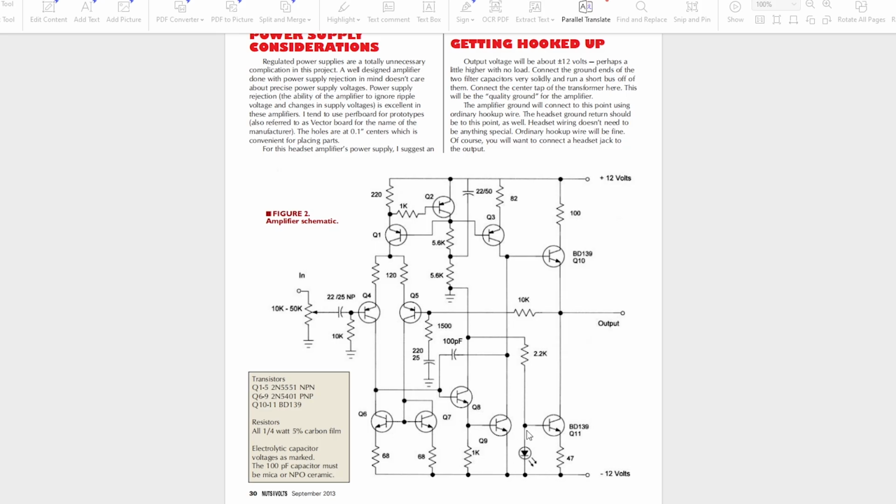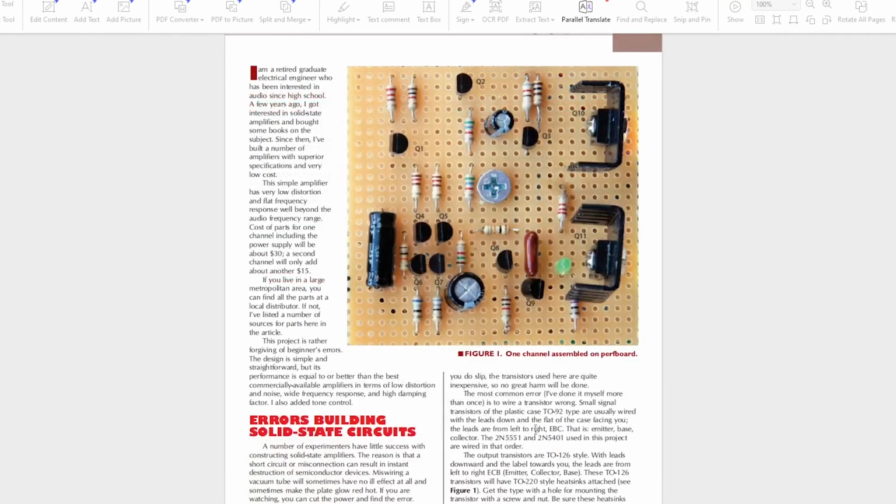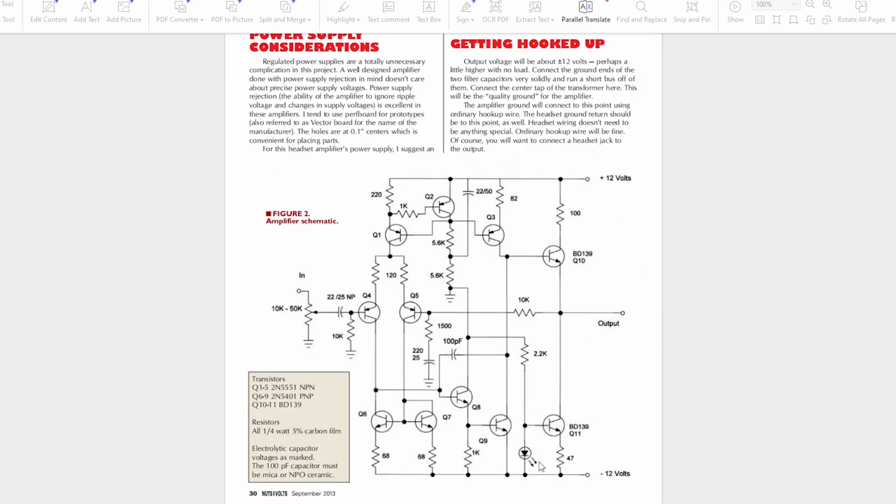Now with this LED, this is quite important. It needs to be an LED with a forward voltage of around 2.1 volts, because this voltage reference dictates what the current is going to be. And looking up further here at his perf board layout, he's just using what looks like a standard green 3mm 40 mcd LED. And I've looked these up on Jaycar. The forward voltage roughly is 2.3 volts, which is the ones I've got. And if you use a different color LED, well, you're going to get a different forward voltage. So yeah, you can't really change the color.